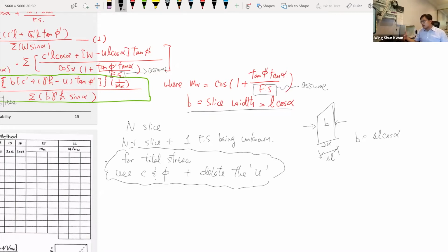So if I'm responsible for 50%, or I need to get more accurate work, then I will go to computation work like this, which can cost me days to get done. From setting up the drawings correctly, I need to work with the CAD technicians, make sure I get the CAD files correct, and make sure to review all the boring logs, make sure the groundwater table is correct, and review all the lab test results.